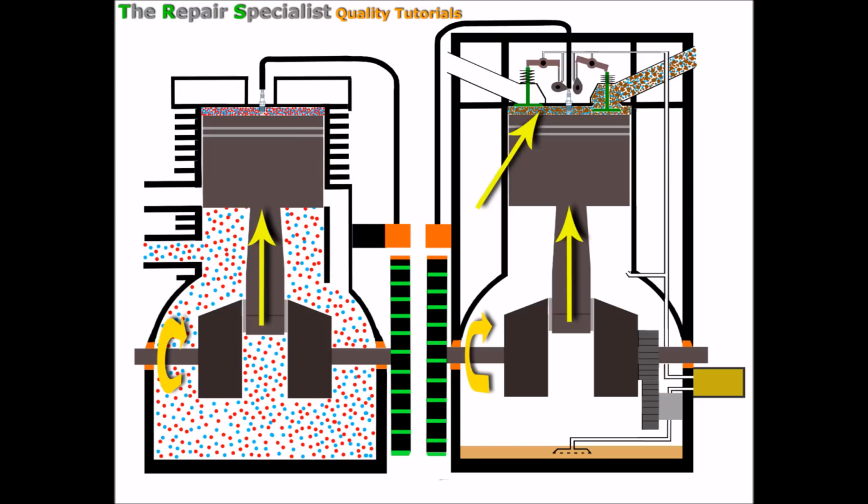The four-stroke piston is forcing out the remaining exhaust fumes, and the two-stroke piston has compressed all that air and fuel together, ready for the explosion of combustion. And at the same time, as it travelled up, it drew in all of that air and fuel and got a good concentration of it down there, waiting for the next cycle. Again, that doesn't happen here in the four-stroke.